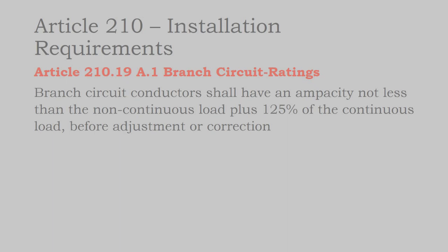Their starting point is an elevated temperature, as opposed to the non-continuous load that is usually off but occasionally turns on for no more than 3 hours. And so for non-continuous loads, you may not have the extra ampacity requirement that continuous loads have.